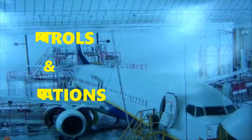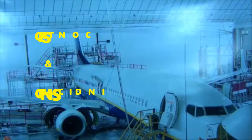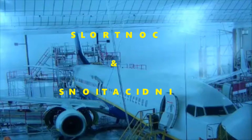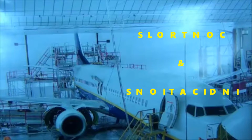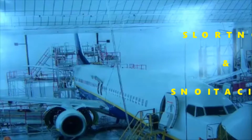Now, besides that panel, you're also going to see the displays on the ECAM. Right, so ECAM's going to show different things. The ECAM has a fuel page, just like we have our HYD page for hydraulics. We have the fuel page for the fuel system, and that's going to show different things. Obviously, your fuel flow and distribution.